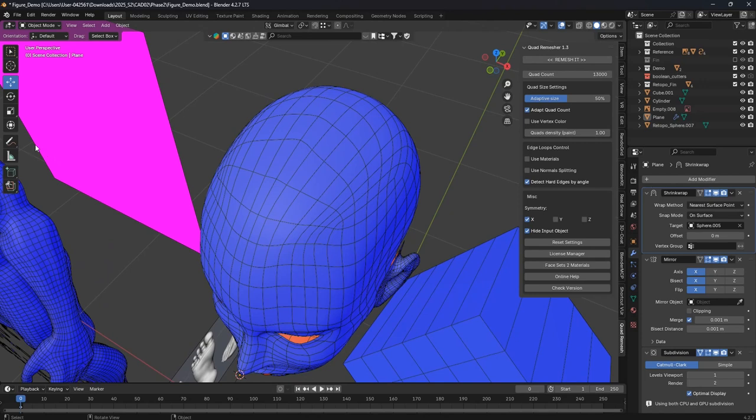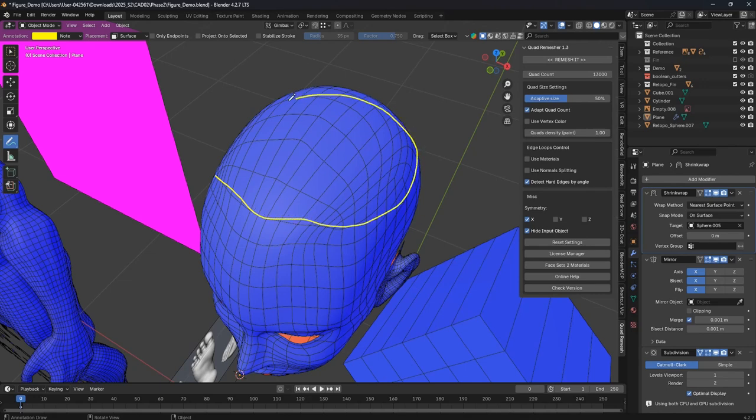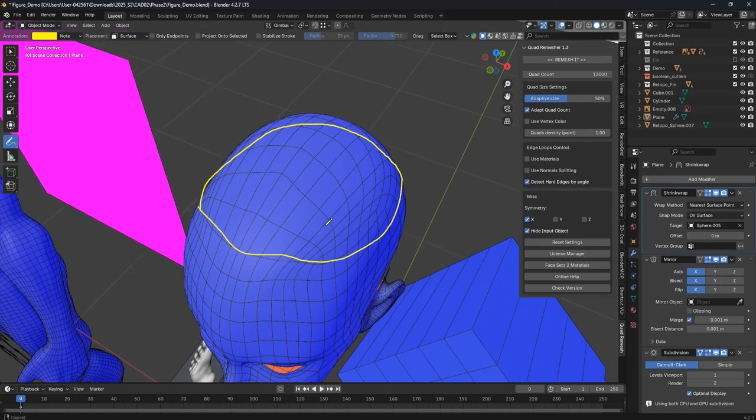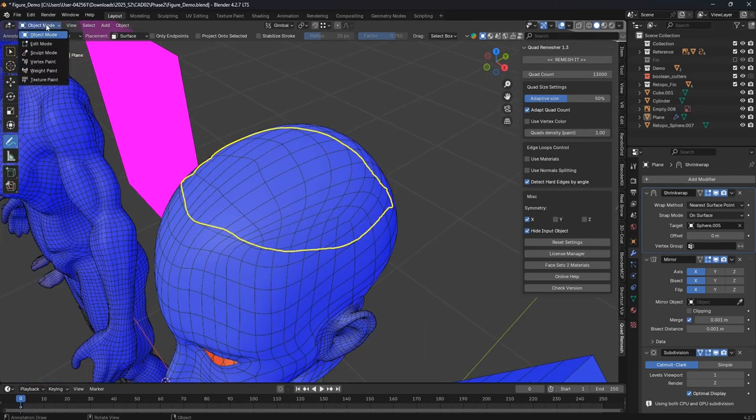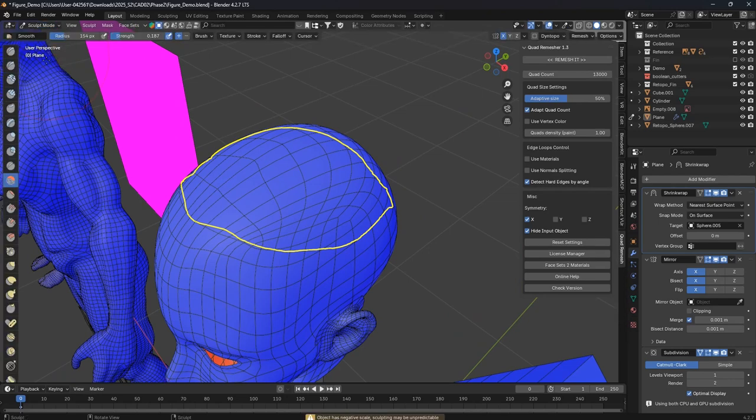Once I finish this area, I have already used the technique I taught you before, using the F key to connect the hole and also using the loop cut to increase the number of segments. Finally merge them together. So here is the result. Some part probably is not that smooth at all, so you can try to use the sculpting tool to refine the topologies. So let's go to sculpting mode.